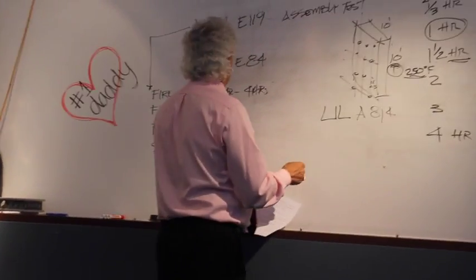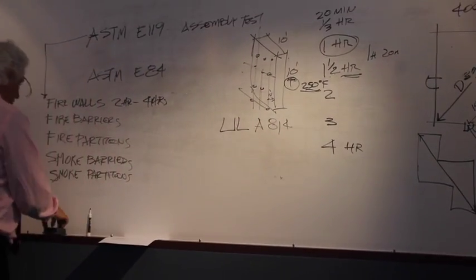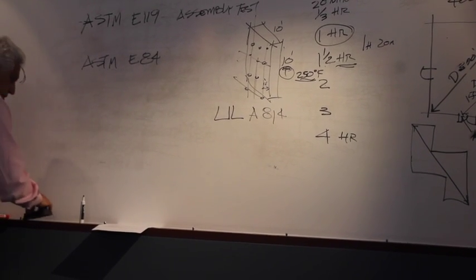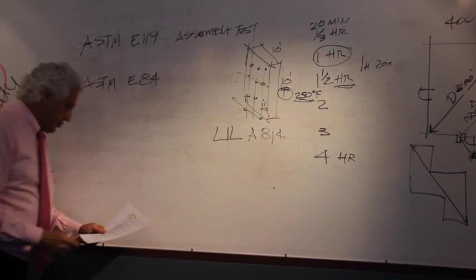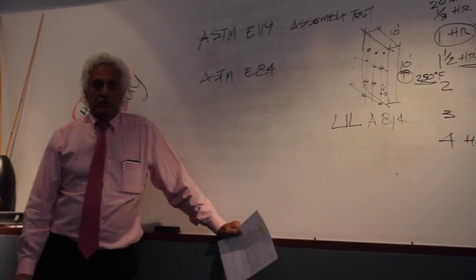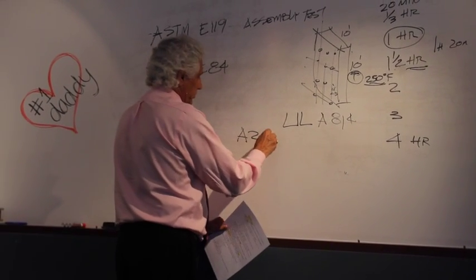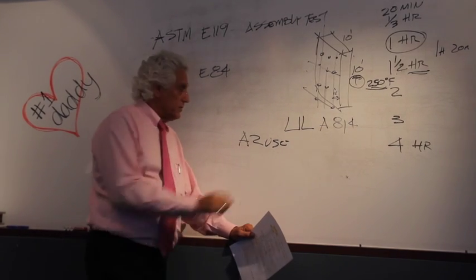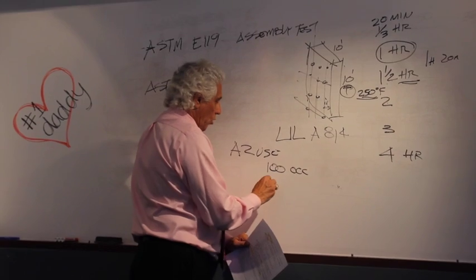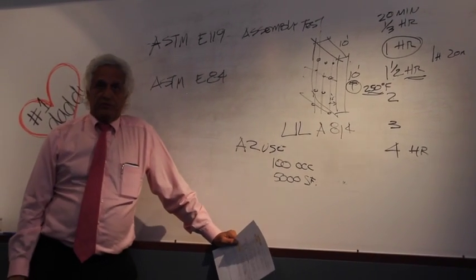We talked about the sprinkler building, and that is the fire protection that we were talking about, that the code so much loves. And so what they've done is they've required that certain uses require that it be sprinkled. By example, if you have an A2 use group, which is a restaurant, and if you exceed 100 occupants or 5,000 square feet, you have to sprinkle that space.